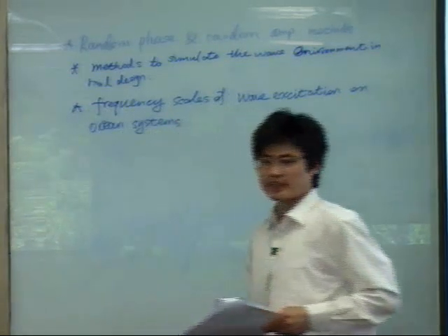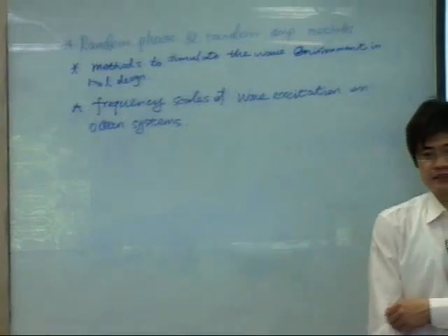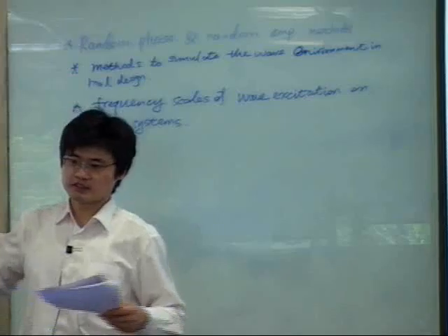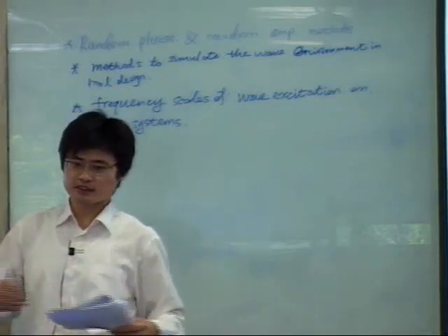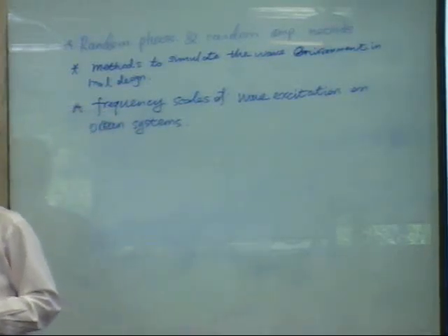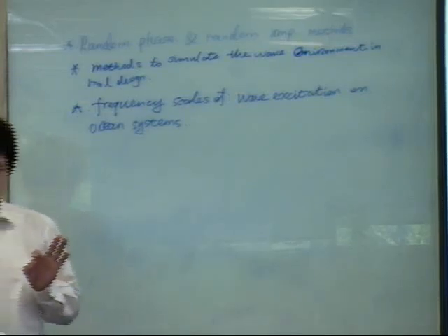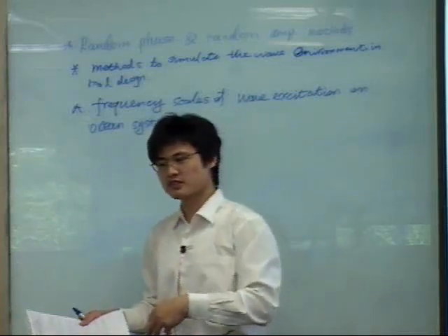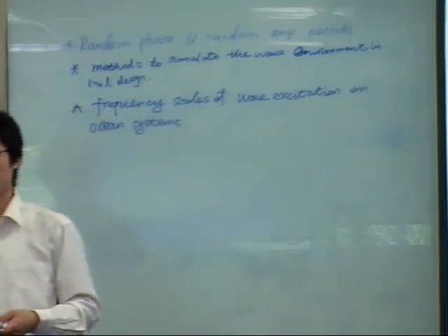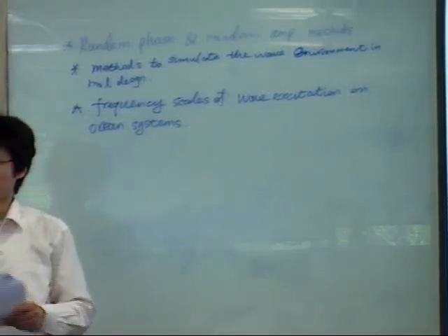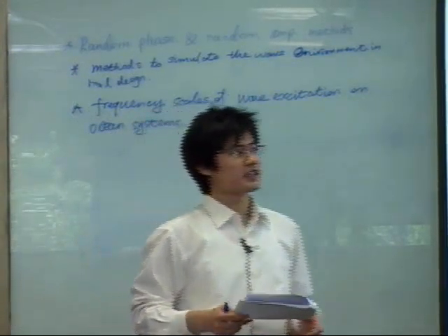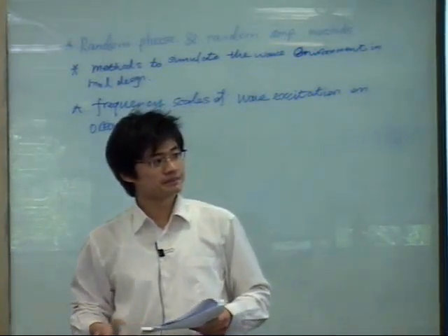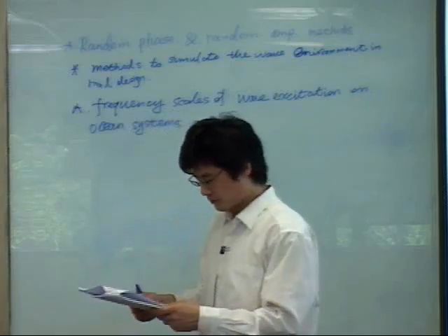I'm sure you all had a structural dynamics class, right? You have a structure, you have forces. The important thing is the frequencies of the exciting force. If the frequency of the external force matches the natural frequency of the structure, you have a resonance. You expect a large response from the structure. And in design, in reality, you want to avoid that scenario.